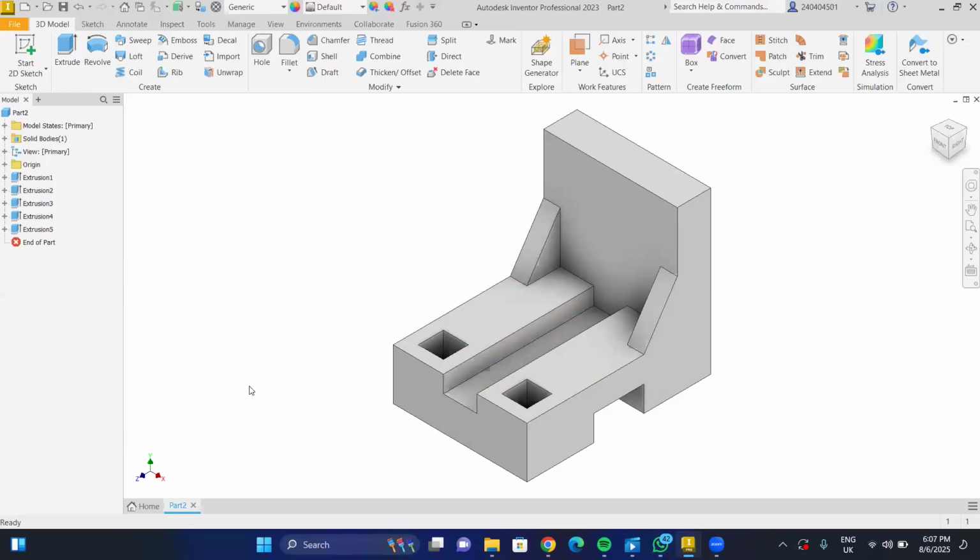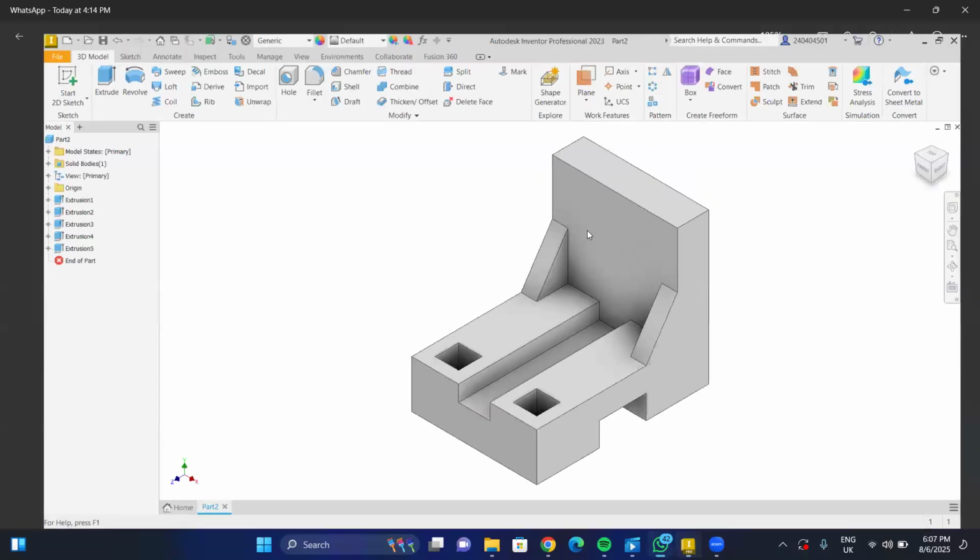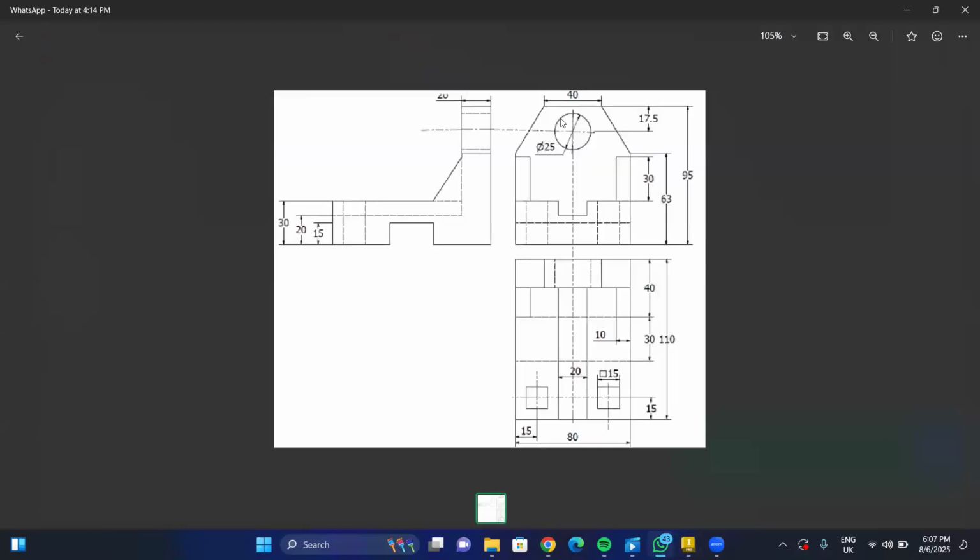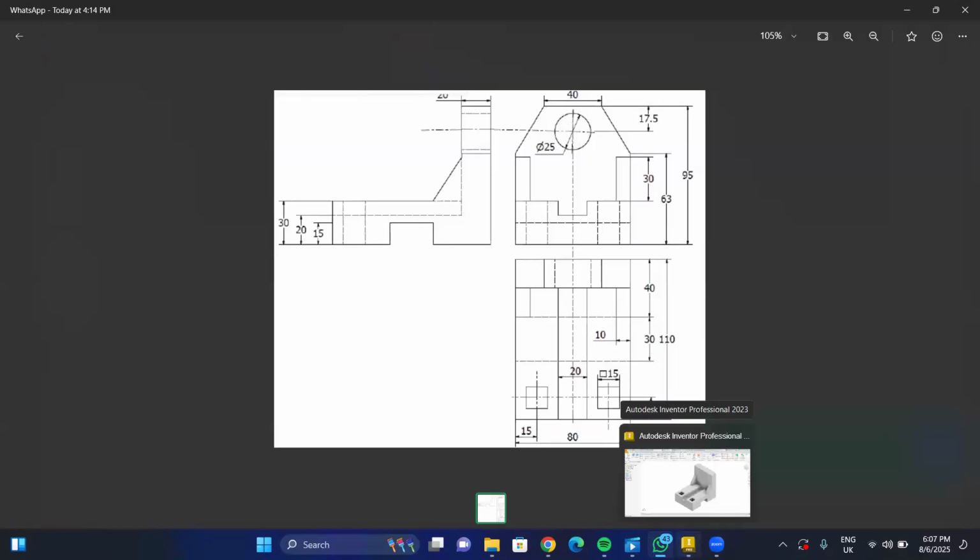All right. Now, the last thing remaining on this diagram, just one small thing, is this and this circle here. So we need to locate the center of the circle of 20 diameter, and just cut this. There's a height of 63 to this place where this one starts from. So the two can go together. So let me do this.